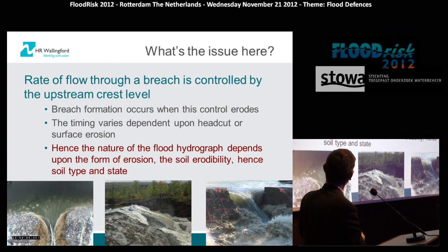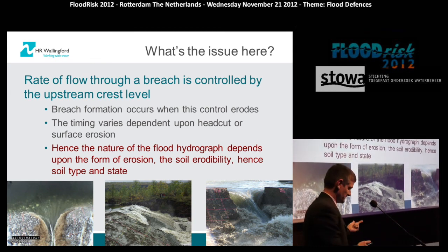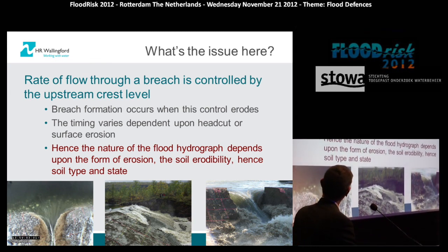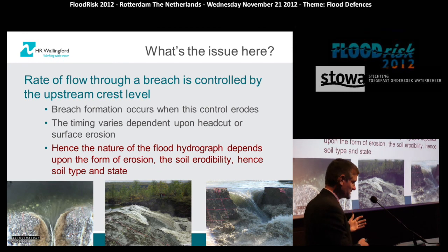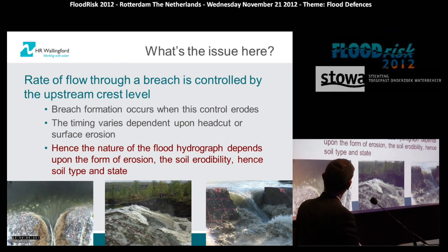So what's the point here? Why is it so important? Well, it's all about when the hydraulic control point erodes. When you have head cut, you pretty much have steady discharge over the top of the levee because the crest isn't eroding until the point where it breaks through, and then you'll get a sudden surge.